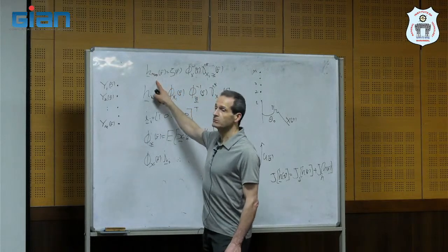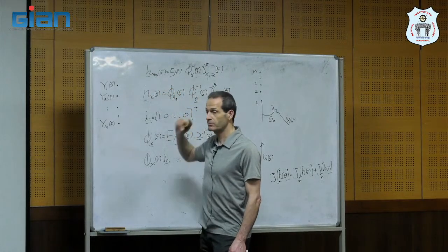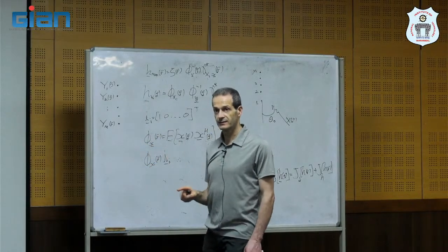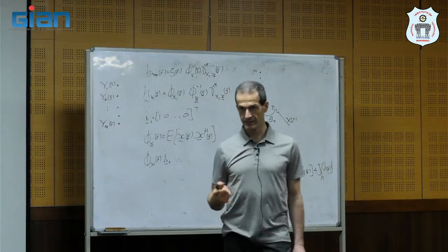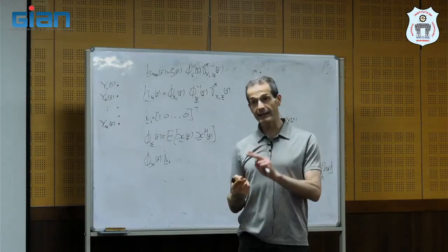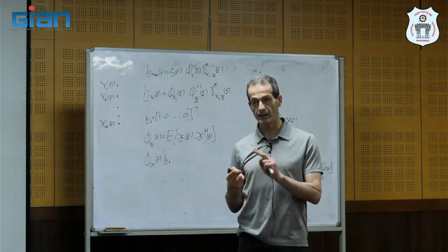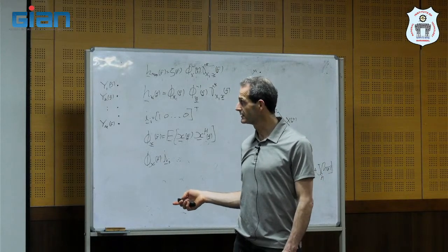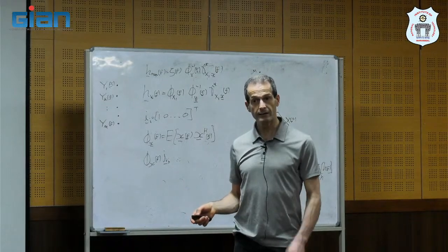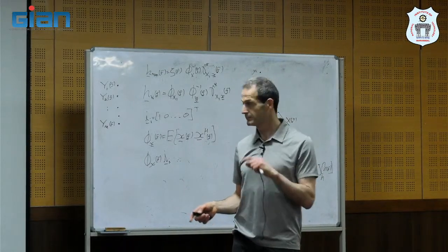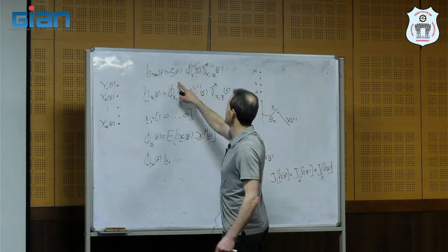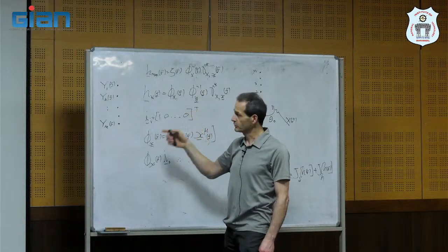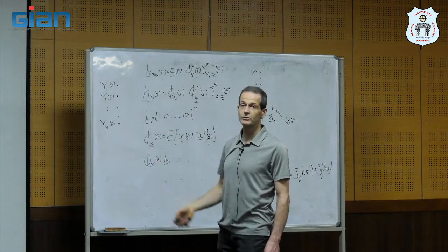some relationship between the Wiener filter and the maximum output SNR filter, which means that the Wiener filter not only minimizes the narrowband and the broadband output mean squared error, it also maximizes the narrowband output SNR, because it looks like this.